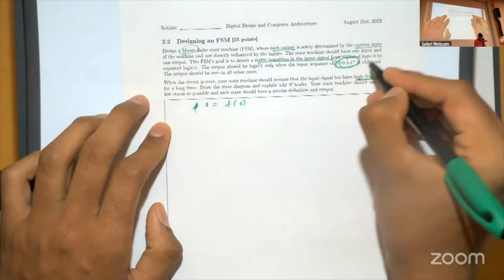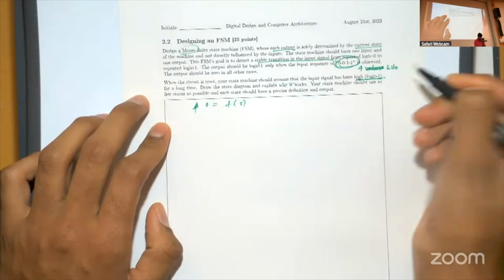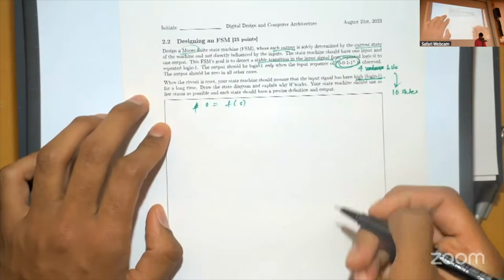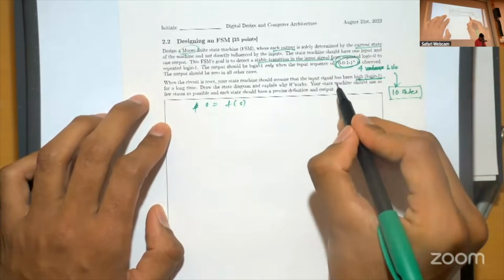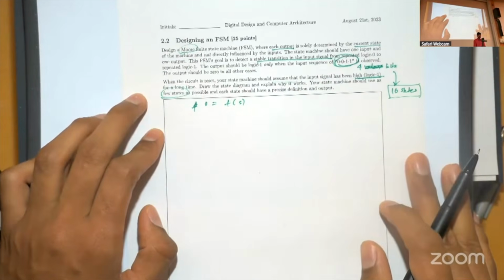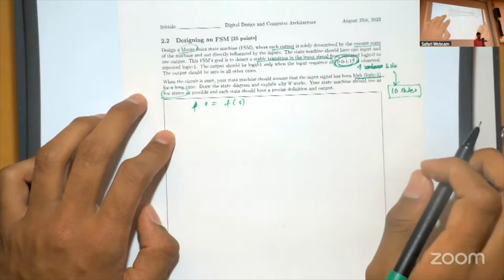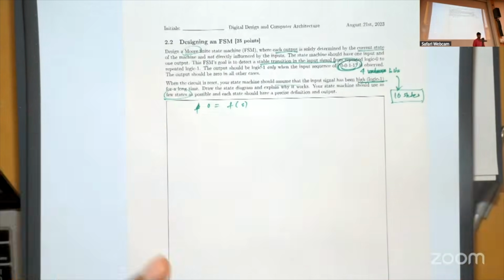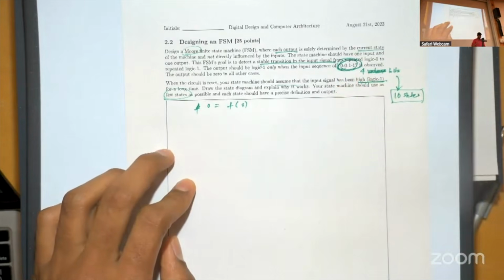You can see that you have 4 values here. Well, 4 bits, which means that you can have up to 16 states, correct? This is the brute force solution, and this is not what we're looking for. We're looking for the fewest states possible. And what you will notice is that you can think of this in a sequential manner. So let's start with putting up all the states that we can think of, and we will come to the solution. Clearly, we need the state that identifies 0, 0, 1, 1.